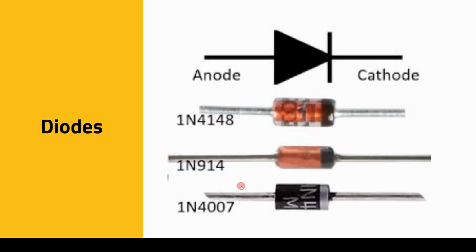So yeah, let's look at a couple of these common types of diodes. This is the symbol for it. The black one you've already seen, but you also get little glass encapsulated diodes like these. Usually the glass ones use a material known as germanium. It's not commonly used nowadays in most other semiconductors besides these kinds of diodes, and the black ones are usually silicon diodes.